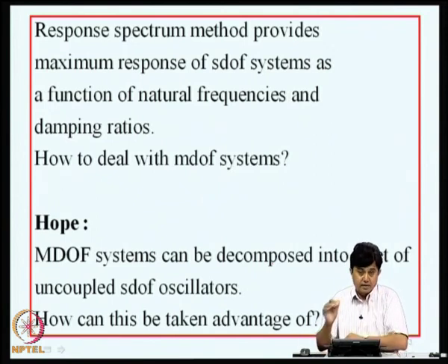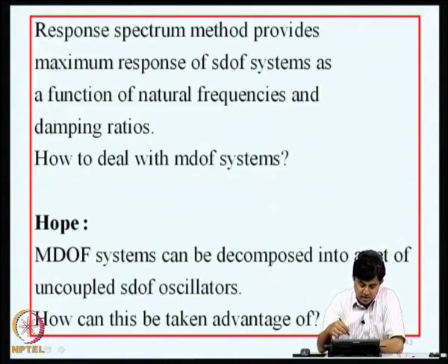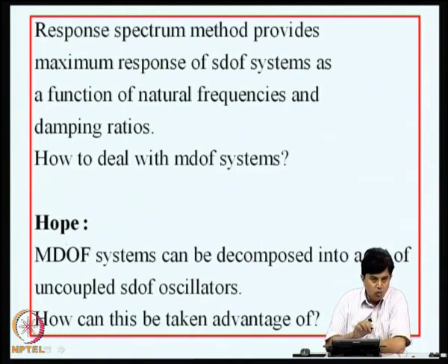Now, in our discussion on response spectrum, what we have done so far is that we have considered the response of single degree freedom systems to the given ground motions. So, the response spectrum method provides maximum response of SDOF systems as a function of natural frequencies and damping ratios. Now, we seldom need to consider single degree freedom systems; often we have to deal with multi degree freedom systems. So, how do we deal with multi degree freedom systems when earthquake loads are specified as a set of response spectra? Now, the hope here is